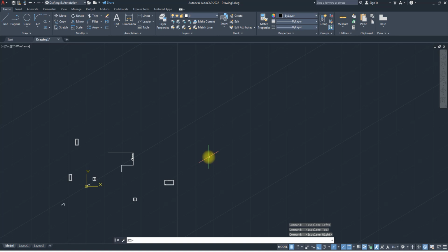Another thing you also need to know in isometric snap is that it is not just like a rectangular snap where you can create any drawing tools, like line, polyline, arc, spline, all those things. Isometric snap has constraints. Not that I can't create those things, but it will not give you an accurate result. So what we usually use in isometric snap is either line or polyline.